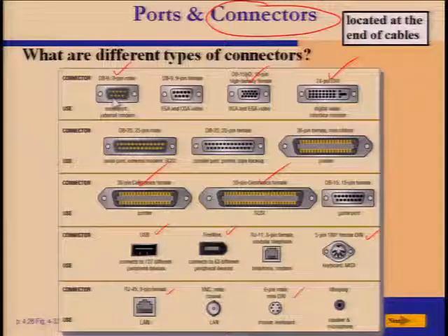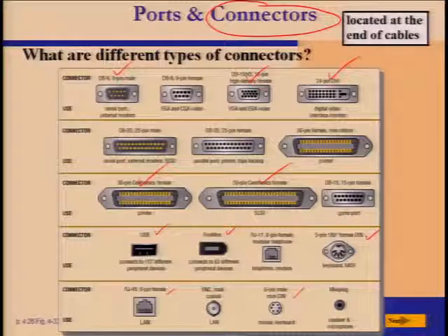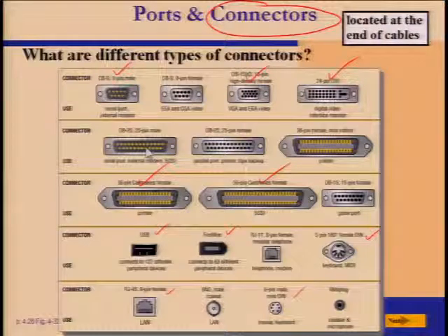When you ask why so many pins can do it, when a small number of pins can also do it, I think this one is a little bit overdoing, right? 25 pins, many of the pins are not used. Because remember, serial communication only needs what? The 2 passages only, to and fro, right? So not so many pins. Most of the pins are not used. So sooner or later they found that this was overkill, so they reduced it to 9 pins. In fact, even with the 9 pins, some of the pins are not used, right?